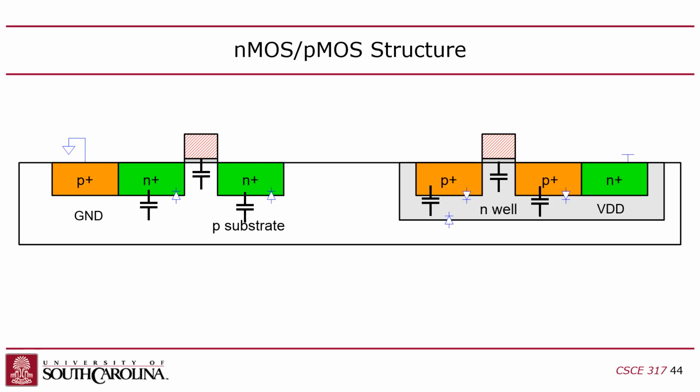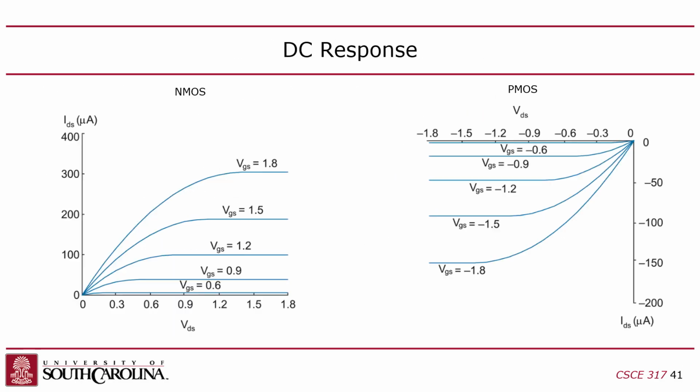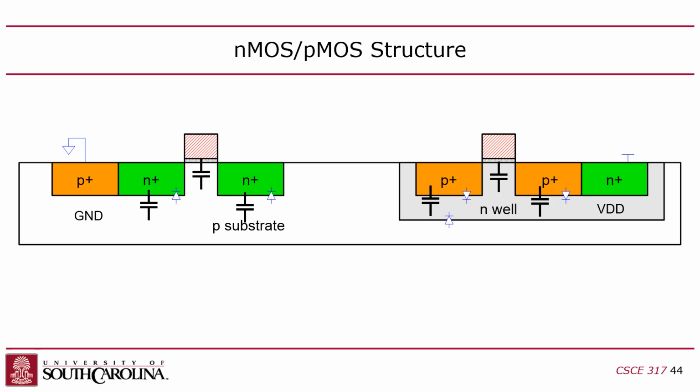However, there is a consequence of doing that. The consequence is that if you make the width bigger, you also make the width of the channel bigger. You also make the width of the gate bigger, right? Now, I'm assuming we're doing this all uniformly. I could make the width bigger on my driving gate, but keep it small on my downstream gate, the one on the output. But let's say I increase the widths all uniformly. I make all my gates wider.